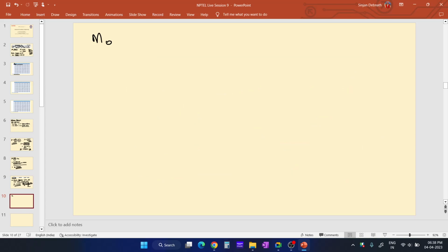First of all we need to find out the amount of counteracting moment. So m0, that is the moment due to fixity, and here the fixity is the pile cap. It is trying to counteract the lateral deformation due to horizontal load h.